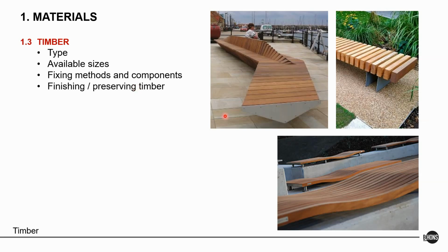And so, as a seat, creosote will make it impossible to sit on. So you'll use that with CCA, which is a greenish kind of surface, but then you have to actually preserve it. And then you can look at sealants that are either oil-based, that you simply paint on and it is absorbed, or a polyurethane-based sealant that's painted on top and then hardens.